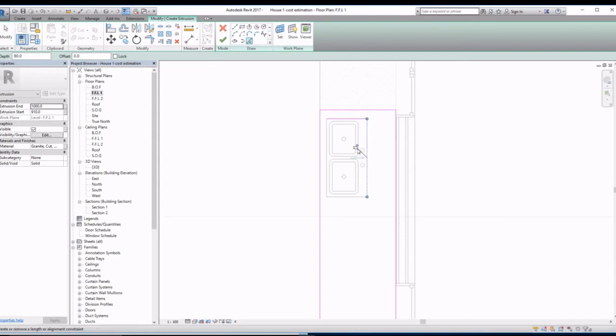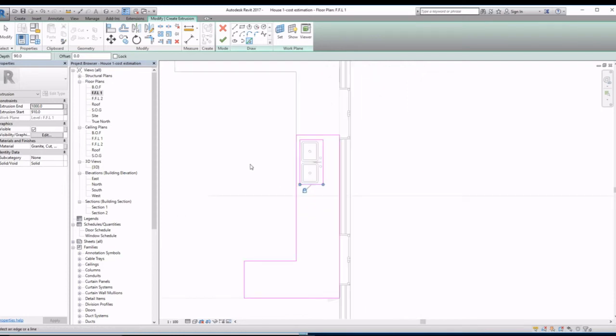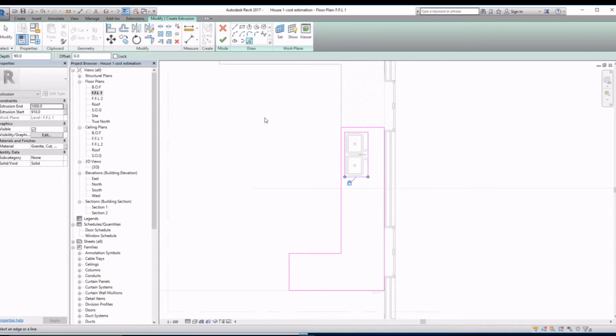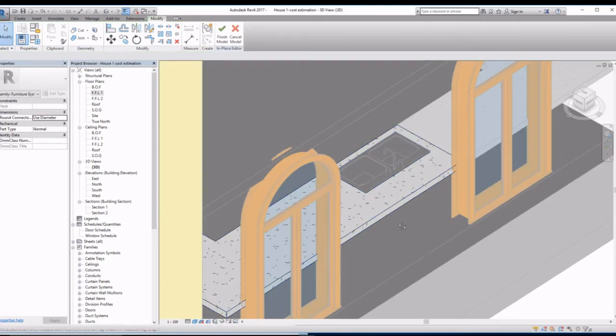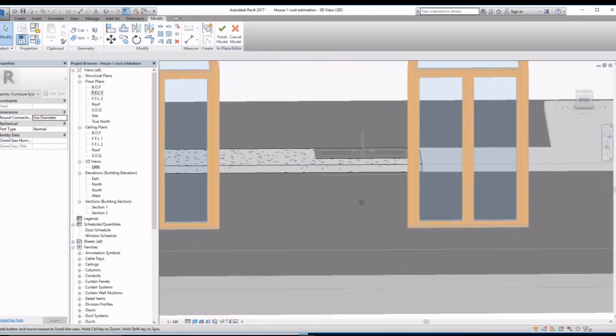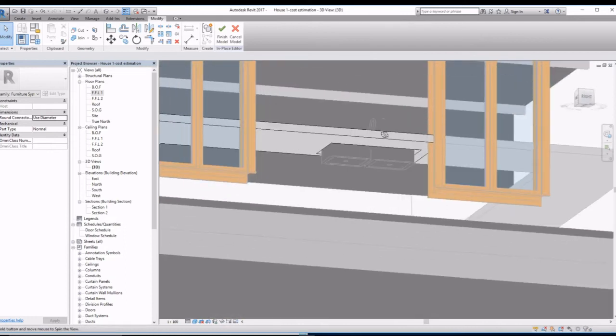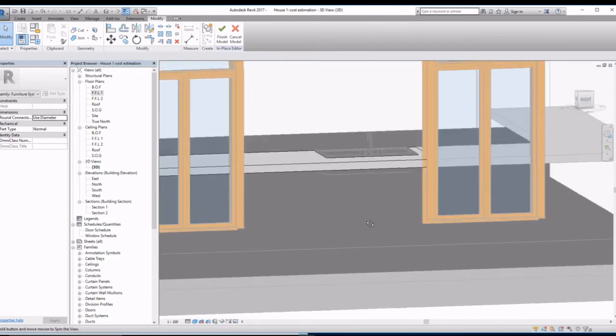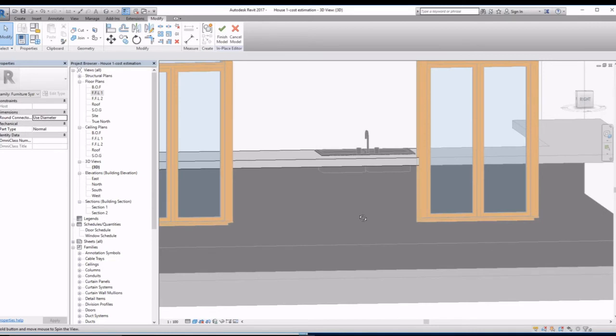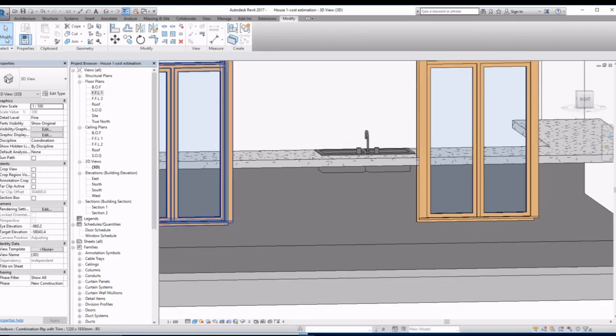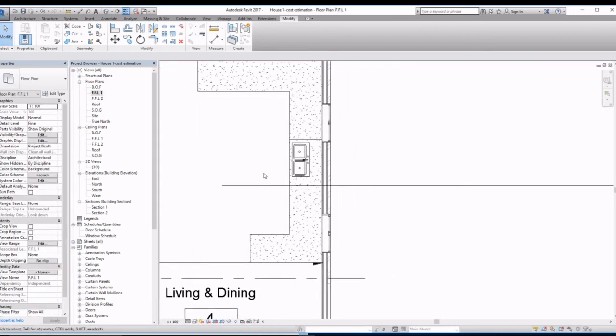And then I gotta highlight the area around the sink as well and lock in your pattern there, because we want to make sure there's no spaces for the water to seep through, just to make it more realistic. And as you can see, we've got now our benchtop with the sink protruding from the bottom. Click on finished model. Let's go back to the floor plan.